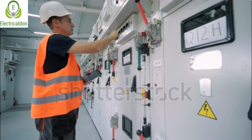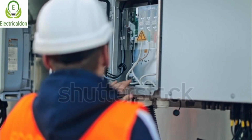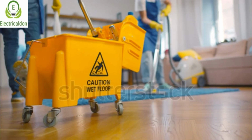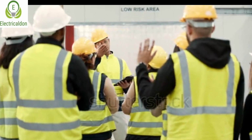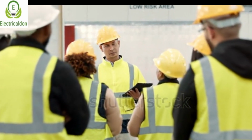7. Preventive measures. Implement preventive maintenance measures to reduce the risk of future electrical faults, such as regular inspections, cleaning, and tightening of connections. Consider upgrading or retrofitting outdated equipment and systems to improve reliability and safety. Provide training to personnel on safe operating practices and procedures for identifying and responding to electrical faults.